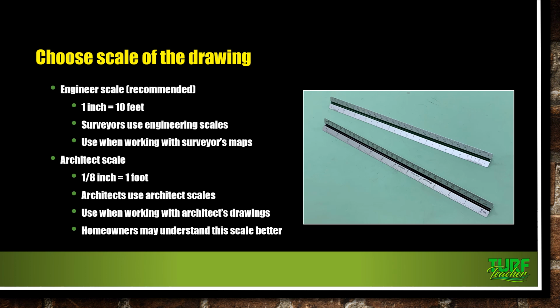And I'll never forget, one day we were on a job site and we were looking at a landscape plan, and Dad's like, we need to scale it, figure out where these trees go. I'm like, hey, I got the scales in the truck. Let me go get them. He said, son, I don't need no scale. I said, what do you mean? He said, it's 1/4 inch equals foot. I got my tape measure right here. He said, 1 inch is 4 feet. That's all I need. I'm like, shoot, never really even thought of that until Dad told me that. So yeah, I would have ran back and got the scales. It's funny. He's like, it doesn't matter if it's an 1/8 scale, 1/4 scale, we can use the tape measure to lay these plants out.